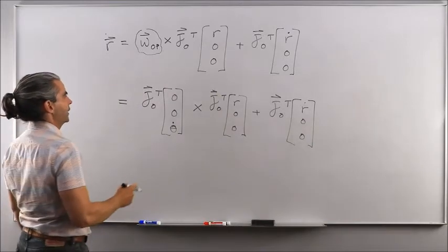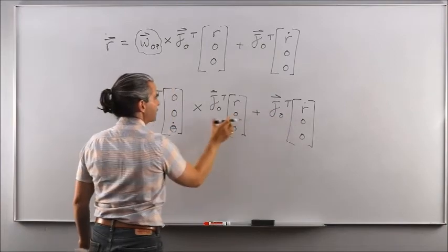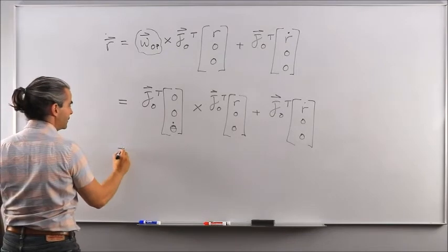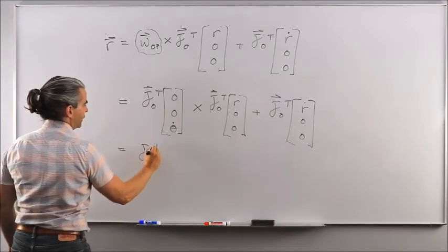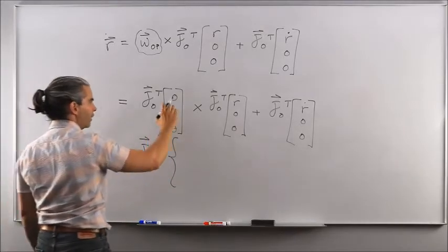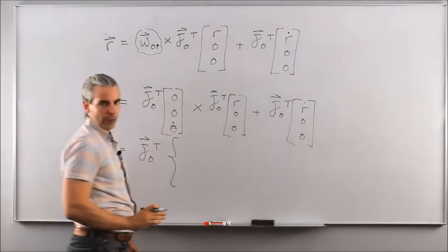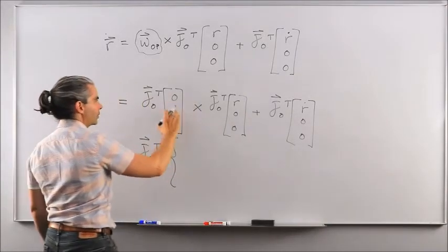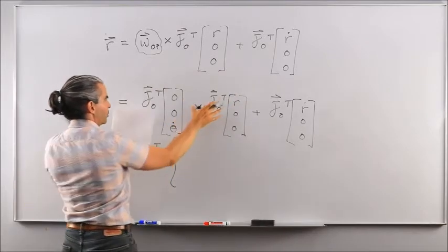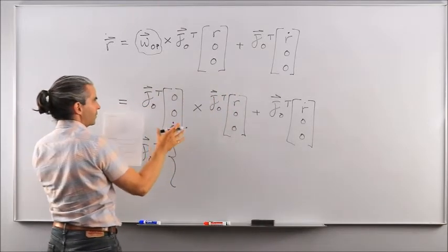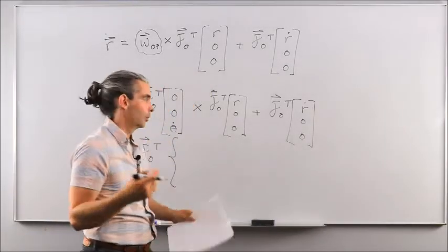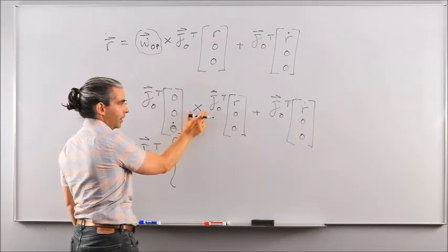Okay, so I can then factor out my Vectrix orbital reference frame transpose out of those three items and write this, which multiplies a bunch of component operations. Here we had the cross product of one vector with another one, but because we took the Vectrix out of it, it becomes a cross product of components. And if you remember chapter 1, cross product cannot be applied to components directly.